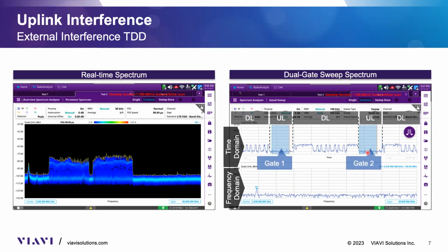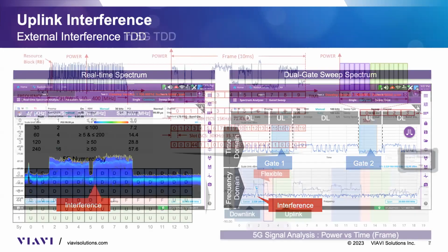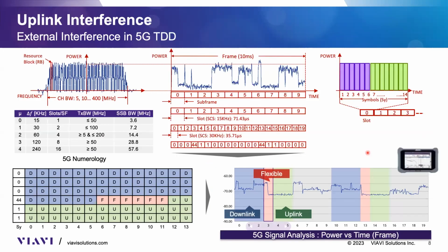So as you can see, we have a couple of gates, so that increases the probability of intercept for interferences. And clearly, we can see now the interference. Okay, that works very well. But what happens with 5G? With 5G, the time that the uplink can be allocated is no longer 1 millisecond or one subframe, but it's much narrower. How much narrower?